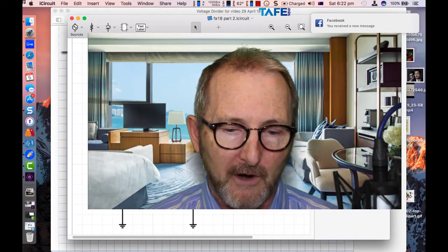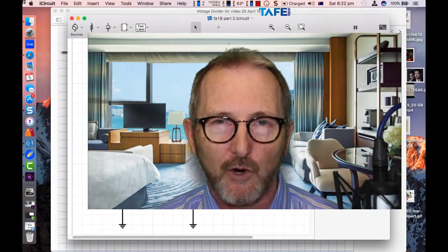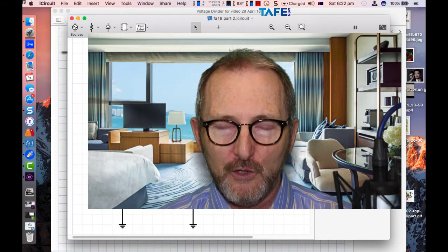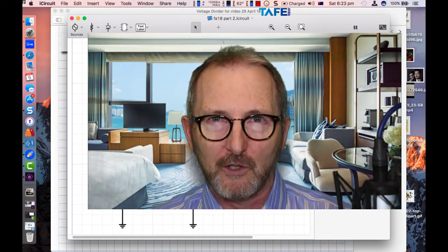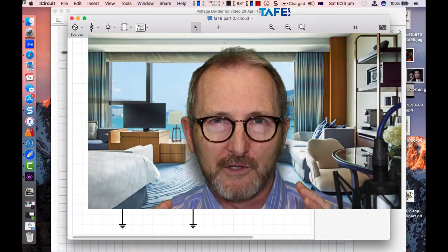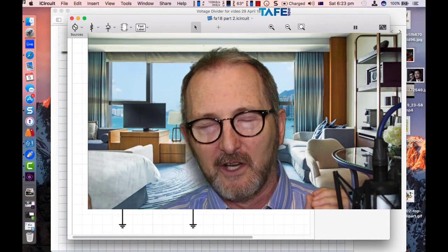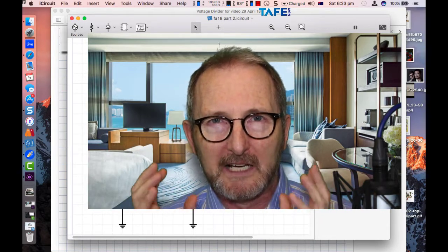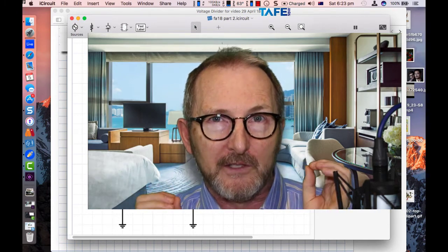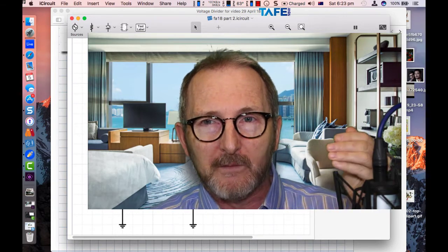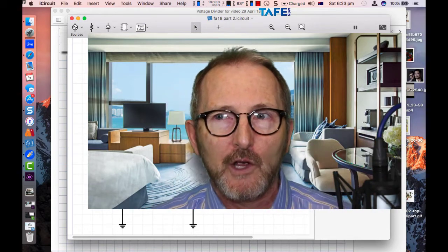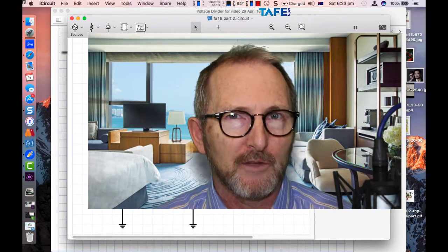All right, a lot of work involved in doing this type of job, as you can see. You have to redraw the circuit. You have to use 3 rules: Kirchhoff's voltage law, Kirchhoff's current law, and current divider. When you redraw the circuit, you've got to start from the furthest end, and then work your way back. You've got to work out R total first, and that'll give you the ability to work out the circuit current total, and then come from the battery voltage side of the circuit and work your way back across, solving all of the branch currents and all of the voltage drops to get